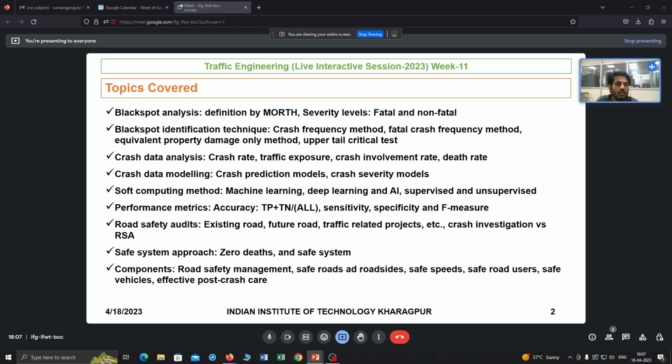The accident has occurred due to the driver's characteristics, his attention problem, sleeping problem, tiredness and other things, but not due to that particular spot or place. So it is not a black spot. The idea of the black spot is that the location characteristics are such that they create a road safety issue, not the other factors.